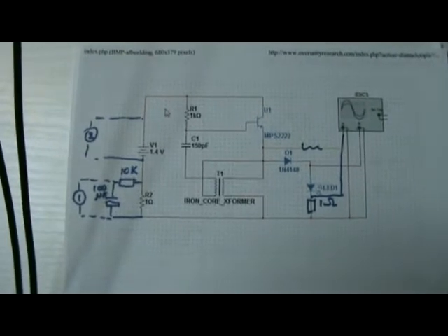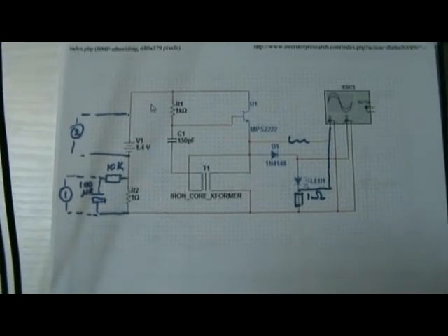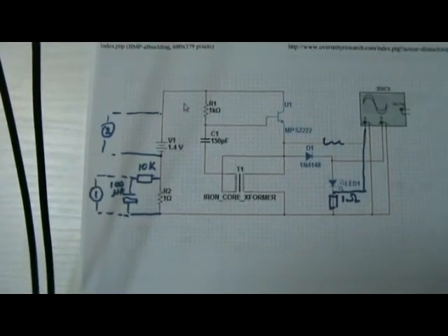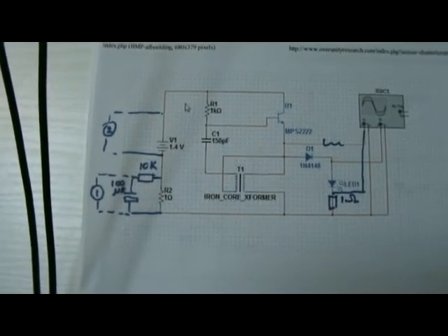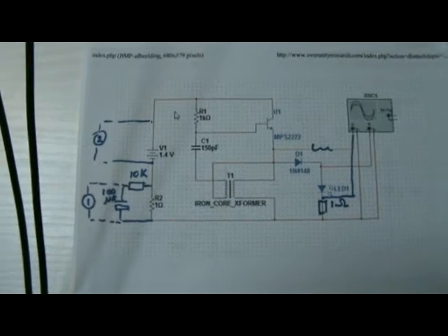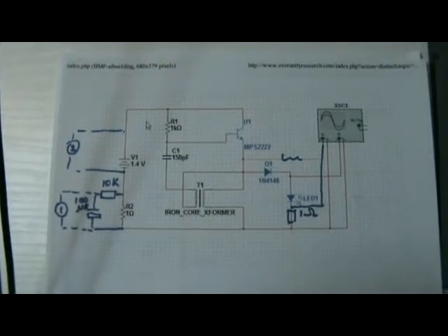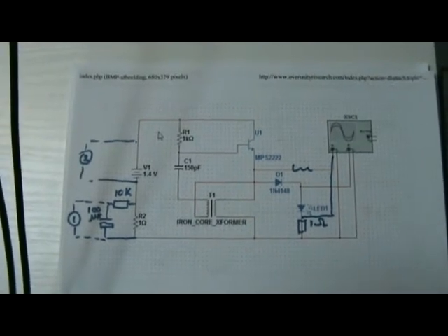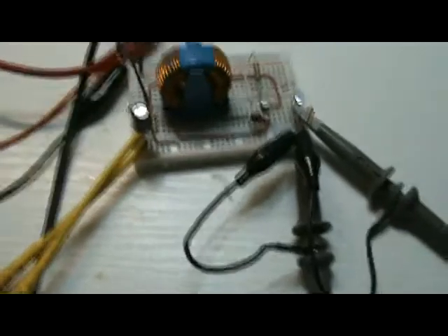I incorporated the dual multimeter input procedure, so I measure across an RC of a 10K and a 100 microfarad capacitor, and the other meter is across the battery. And the output, yeah, that's still the problem. I inserted a 1 ohm resistor there, and I'm doing some scope measurements there. So basically the system looks like this, and in real life it's this circuit.